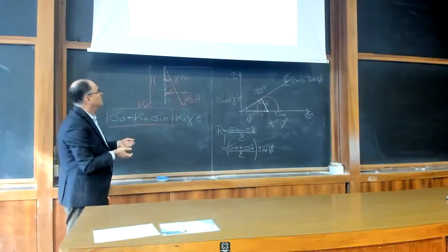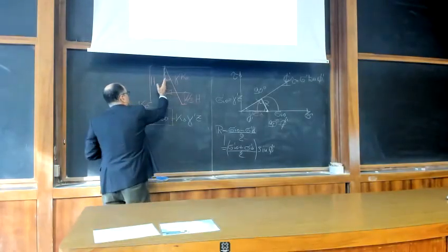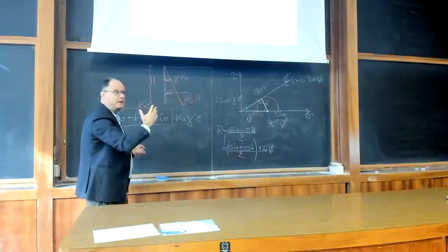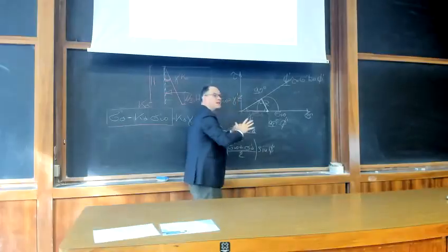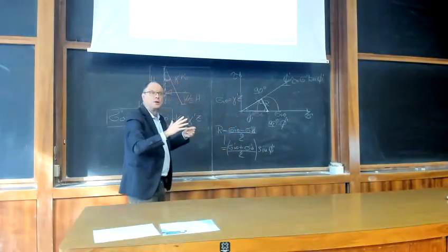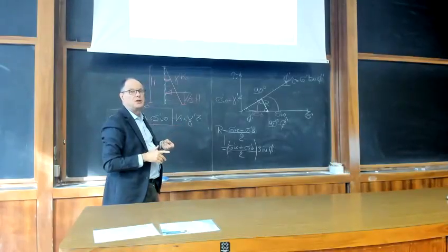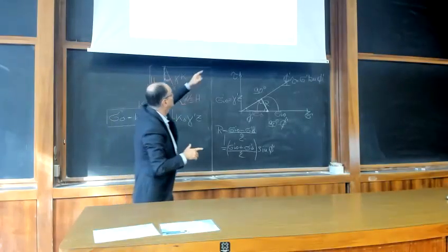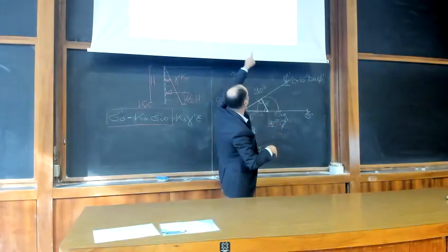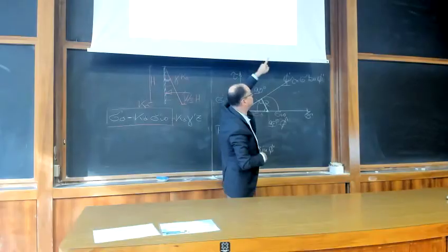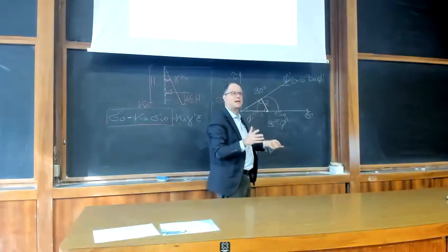Now, once you get to failure, if you keep moving the wall laterally, the soil reaches this, and the soil will tend to slide, to move along those slip planes. Why are these slip planes inclined with the horizontal line by this angle that you can see here, 45 degrees plus phi dash divided by 2? Why exactly that angle?